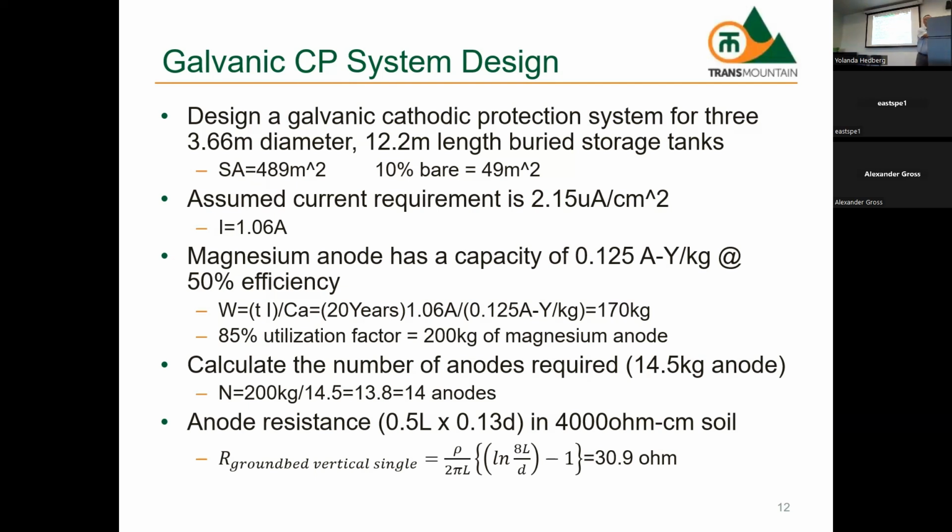But I feel like I could get a difficult job because it's fluctuating, right? So seasonal effects are real. Okay, so depending on the soil environment and how much the resistivity changes, you have to design your CP system accordingly.